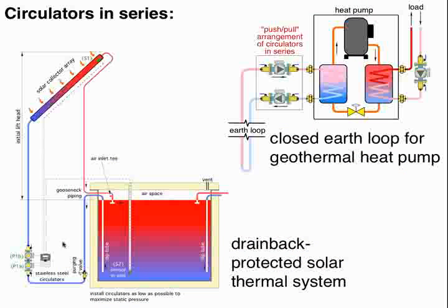This graphic on the left here shows a drain-back system. We need those 2 pumps in series. Well, I say we need it. There are single pump solutions for this today, but customarily, I'll say 2 pumps in series like this was a common approach, and that's because we actually have to lift the fluid from this static level up through the collector.